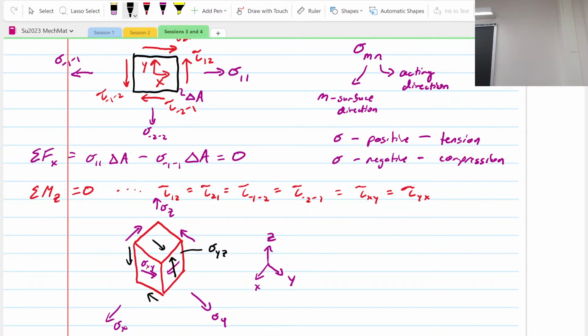There's no force actually acting on it, right? If I put a slice here, there's nothing acting on it, because I'm not using F3. We're only looking at the contribution from F2, because we're doing superposition. So there's no internal force. That means these two members are the ones experiencing the load.